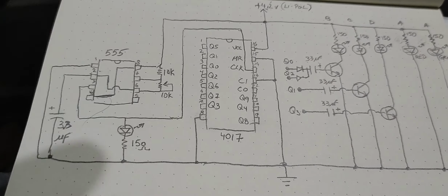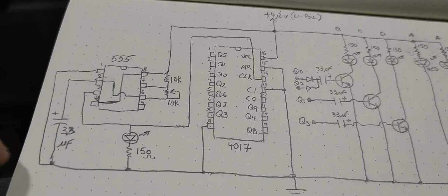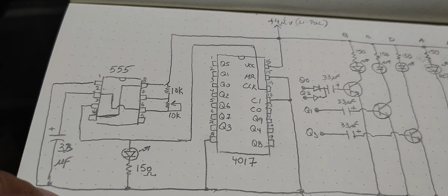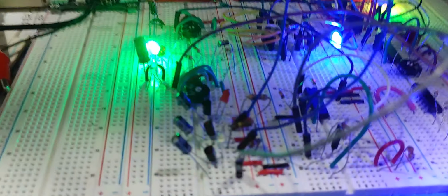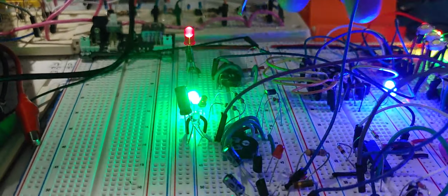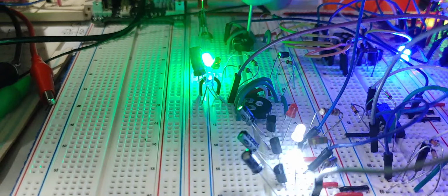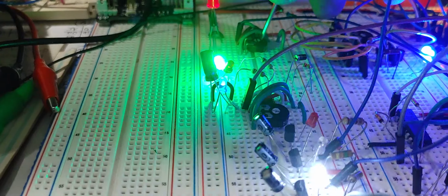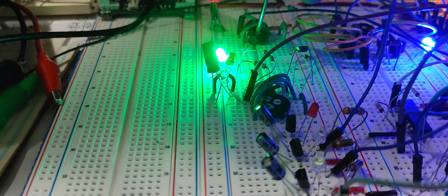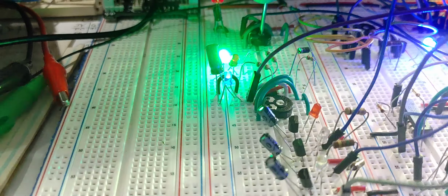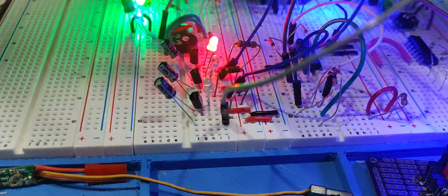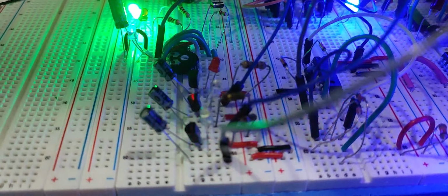This is just a 555 timer circuit that I have set up to give me that variation in pulses here, and I can adjust that 10K potentiometer. It has its own pulse LED there. I can adjust that so it'll give me slower. That's as slow a rate as there is right there, which would be about average.